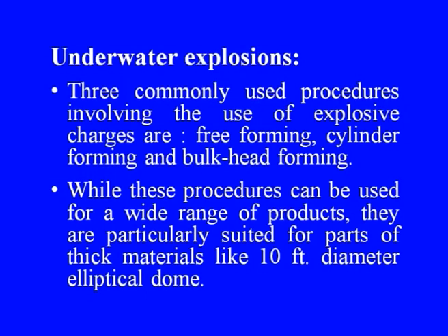3 commonly used procedures involving the use of explosive charges are free forming, cylinder forming, and bulkhead forming. While these procedures can be used for a wide range of products, they are particularly suited for parts of thick materials like a 10 feet diameter elliptical dome, which is considered to be a very big piece to be formed, and this process is found to be suitable for such huge parts to be produced.